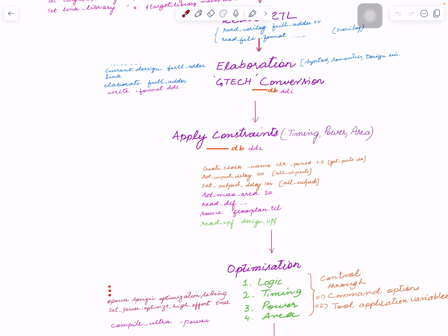But for this video, you need to provide timing constraints, you need to provide area constraints, and you need to provide power constraints. And once you use those constraints and everything is good syntax wise and all that, then it goes into conversion into final netlist and a lot of optimization. Let's stop this video here. This is a lengthy topic and it's fine, I don't want to rush it. But I hope you got the concept of why we apply constraints and at what stage we apply constraints.